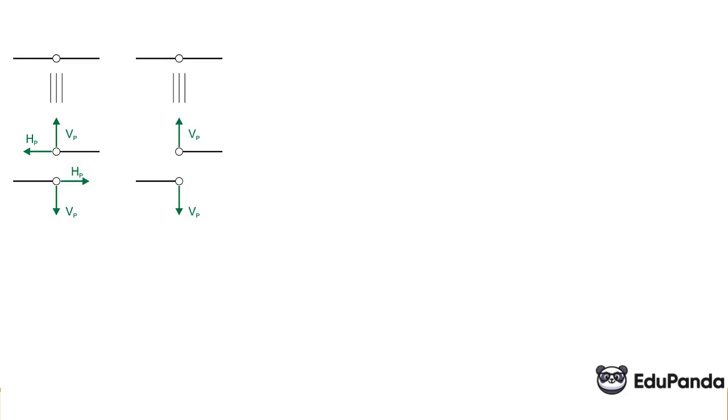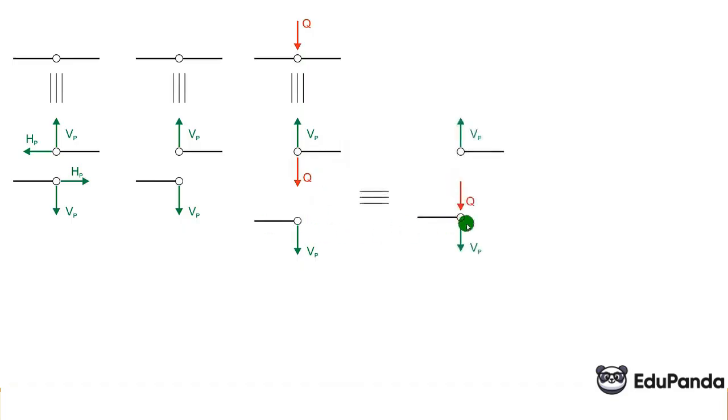And now if there is a shear force applied at the hinge, we only write that shear force in one setup. It can be in the top setup, but it can just as well be in the bottom setup. Here we also have freedom, and when it comes to the applied moment, it must be clearly applied from one side of the joint, either from the right or from the left. Then we do not have a problem determining to which beam it should be transferred later.